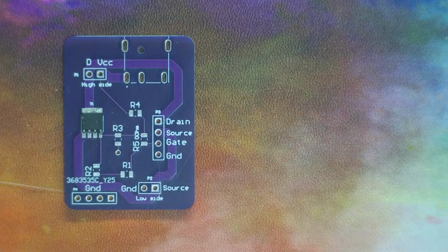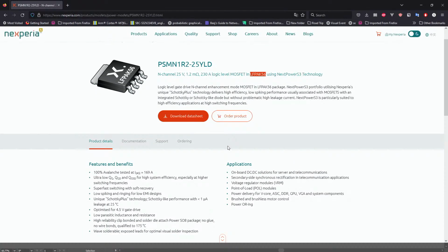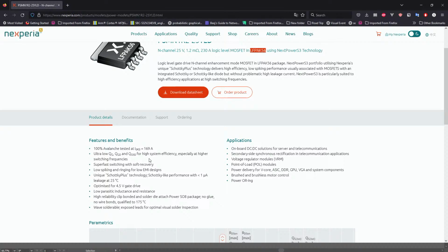This is the packaging. I've used this particular MOSFET to design various different speed controllers, and I found it to be a MOSFET that can help in designing and working with electronic speed controllers, because it can handle high voltage and high currents. This will definitely fit within a 3S battery pack, because 25 volts is way above the 12 or 13 volt range that a 3S battery would provide. And the current that this can handle is quite a lot actually.